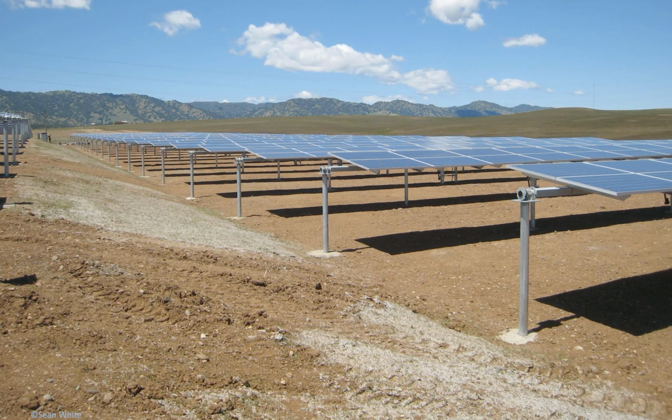Let's talk about the solar energy fundamentals of this system, which is called a single axis tracker. It's a horizontal axis. It points at the sun in the morning, it points at the sun in the afternoon, and at noontime, unless the sun would be straight over your head, it's not pointing at the sun. It's actually flat at noon. They can put a whole bunch of PV on one tracker, and when the PV system is big enough, it will pay to do maintenance on a system like this because you will get extra energy.